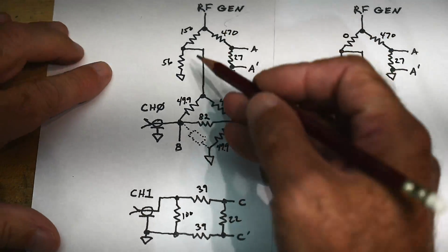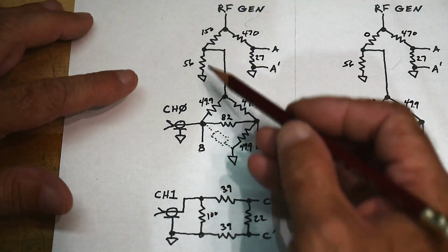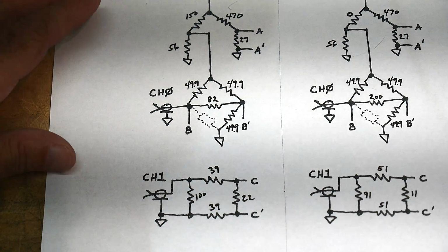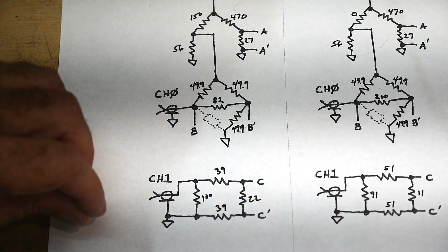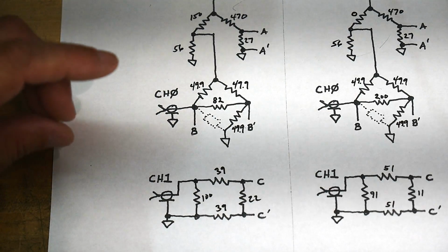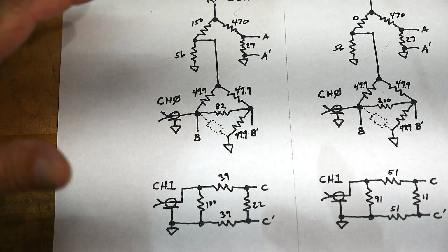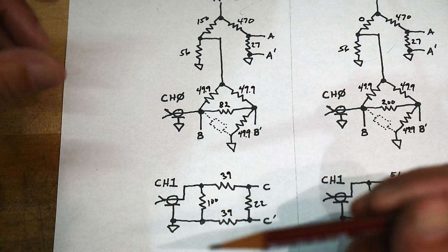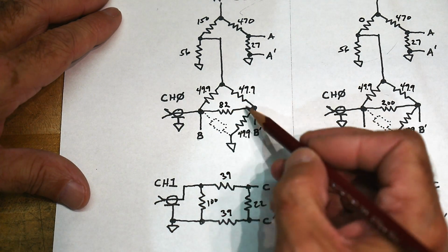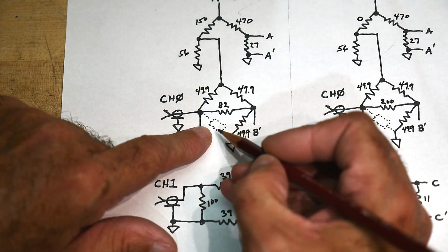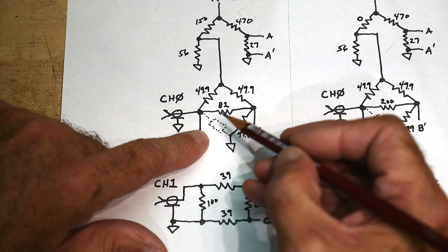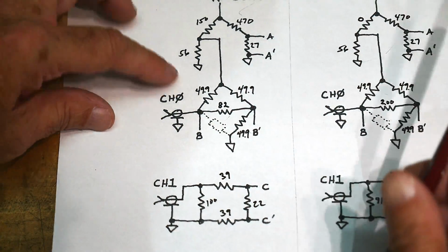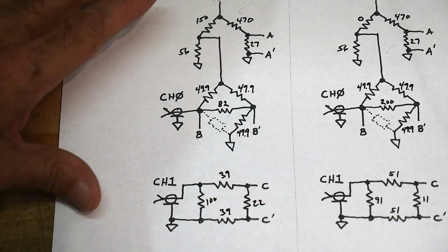It's a pretty simple circuit on the surface. Most of the tricky parts are going to be the mathematics of this whole thing, the calibration of it, and the use of harmonics is a big deal. But the underlying theme here is that it is pretty simple, and you can see how, being used as an antenna analyzer, you're really just putting your antenna into a bridge, and then you're seeing whether that's 50 ohms or not. Then the bridge will balance. If there are any phase shifts, positive phase shifts, you move up the Smith chart. Negative phase shifts, you move down the Smith chart. Hope that all makes sense.